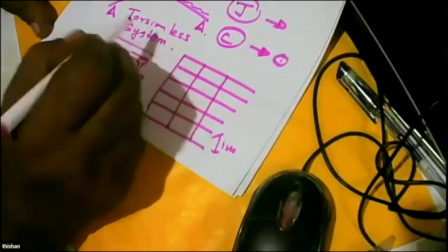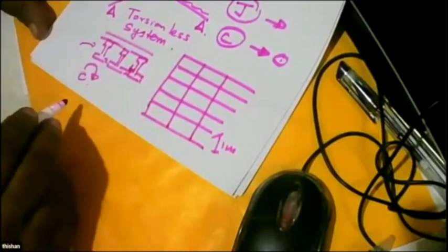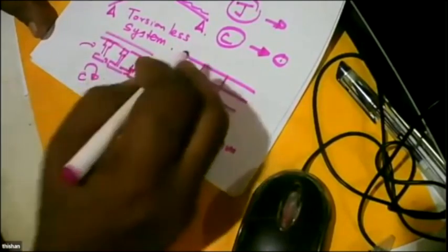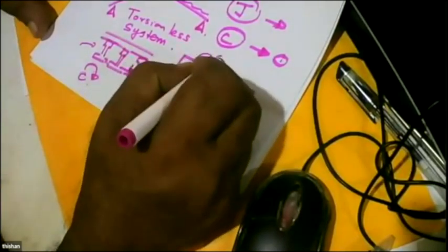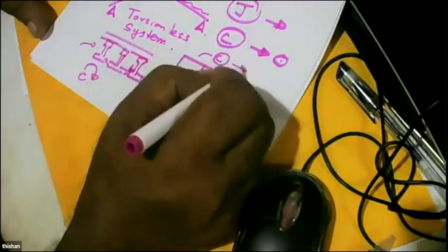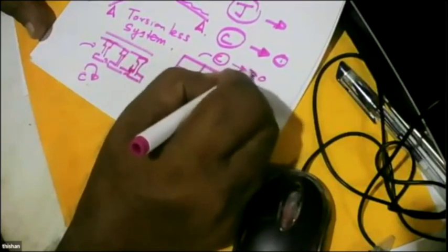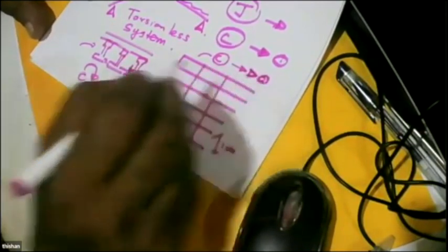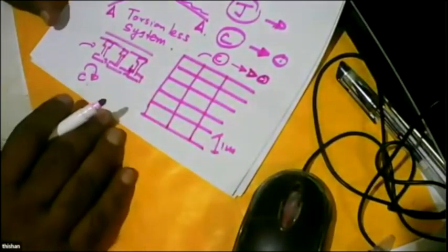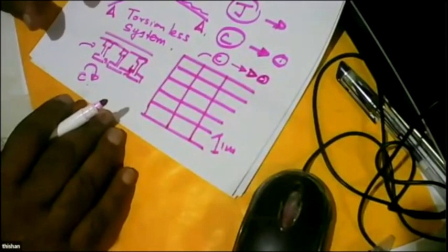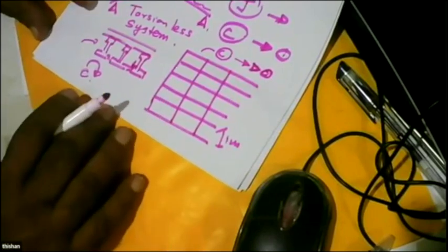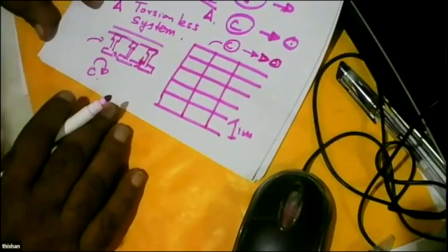How to get a torsionless system? Once you analyze, you should get the answer for torsion as close to 0. For that, we have to say torsional constant of these beams is very low, going closer to 0. So what we do is we allow the program to calculate the torsional constant, then multiply it by something like 0.01. So we bring it down by 100 times. Then we plot the torsional moment and we find it is very small.